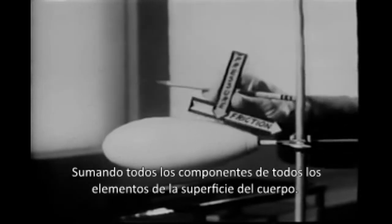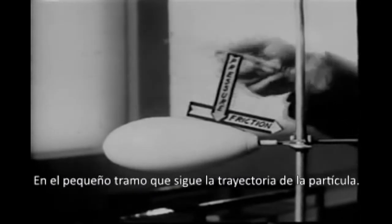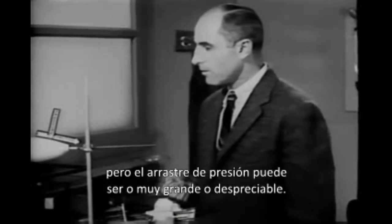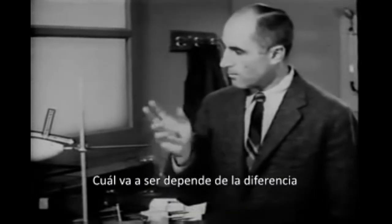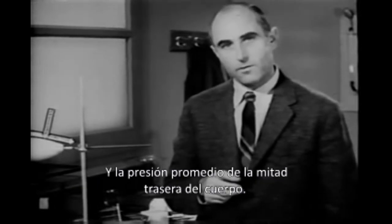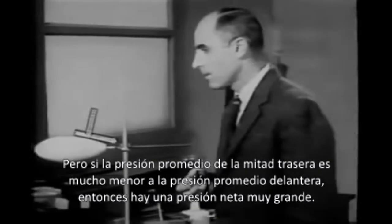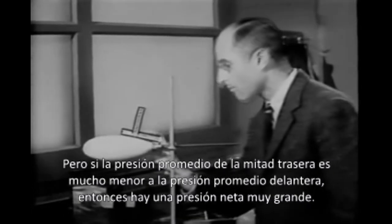Adding up all such components for all elements of the body's surface, we get two contributions to the total drag: pressure drag and friction drag. Friction drag is always present because all fluids have some viscosity, but the pressure drag may be either very large or it might be quite negligible. Which it is depends on the difference between the average pressure on the front half of the body and the average pressure on the rear half of the body. If the average pressure on the rear half is equal to the average pressure on the front half, then the net pressure drag is zero. But if the average pressure on the rear half is much less than the average pressure on the front half, then there is a large net pressure drag.